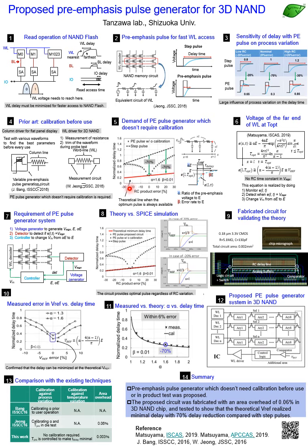This is a graph of the delay time versus RC product error, meaning zero error indicates the target RC value case, and the designers must consider the plus minus 20% variation across the die, or across wafers, or across the lots.